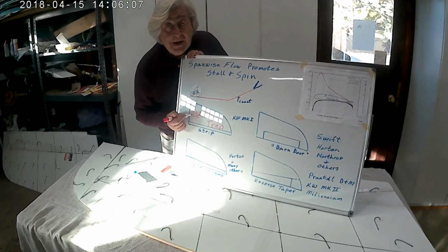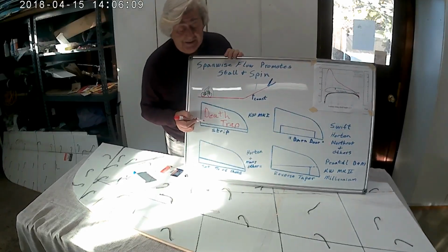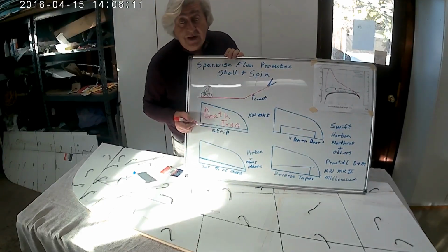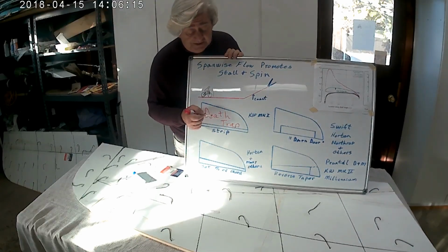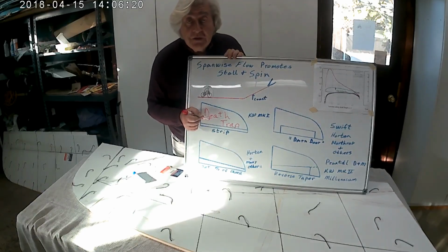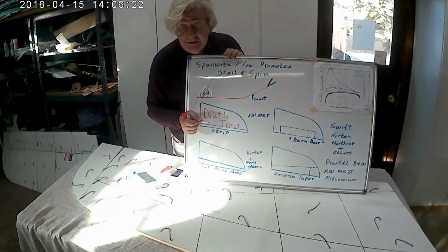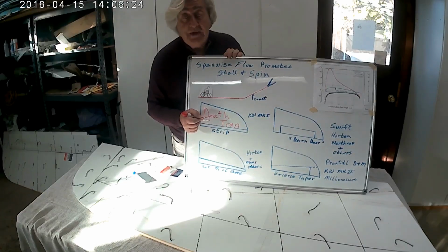It's a death trap. It's really bad. The strip elevons are horrid for flying wings, for swept, tapered flying wings. This is a sure way to an early grave. My original wing, without provocation, at the slightest hint, would break into a spin.